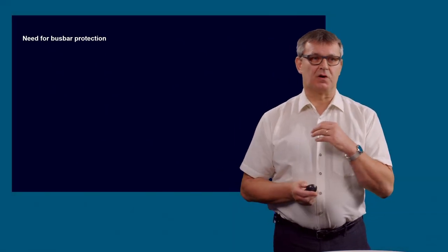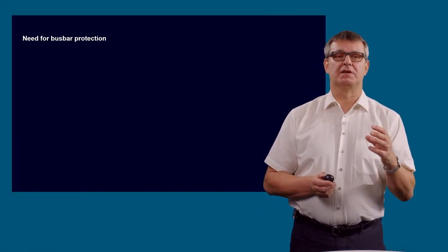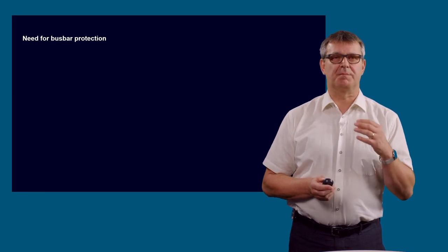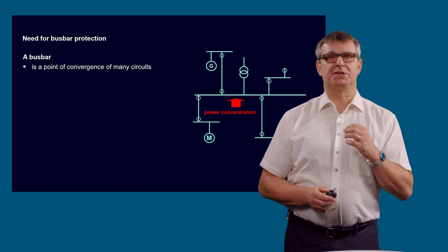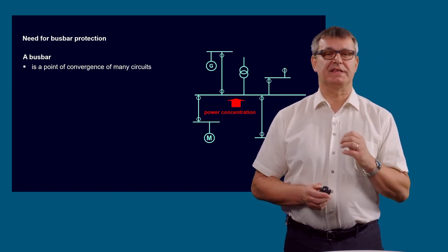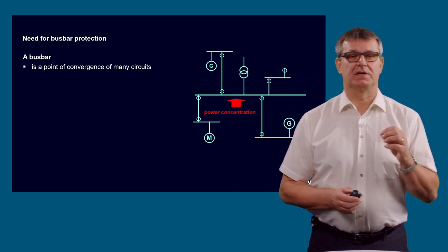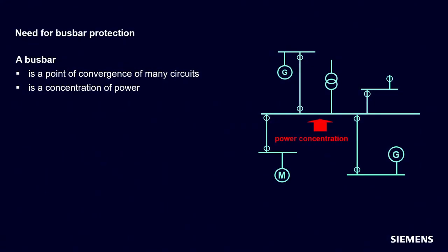That was for protection in general. Why do we need busbar protection? A busbar is really a point of convergence of many circuits. It's a concentration of power, and therefore really high and destructive fault currents can result.